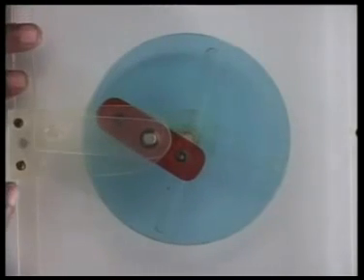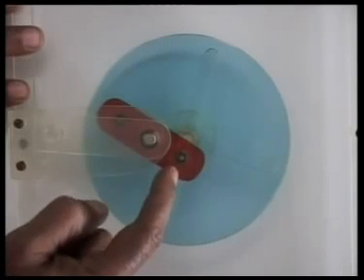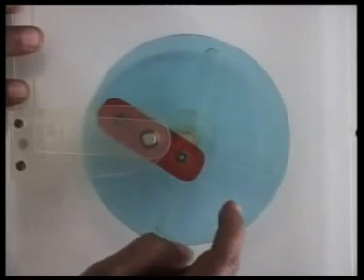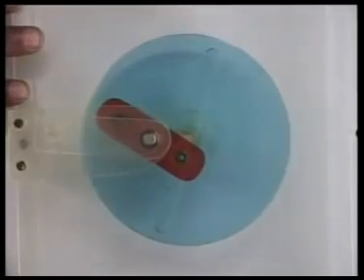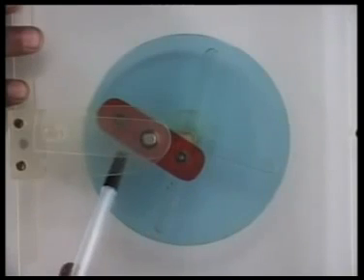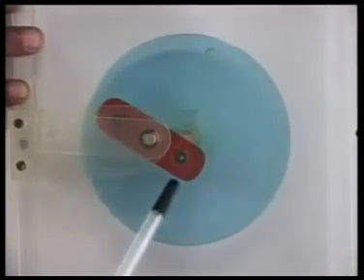Now I shall demonstrate this cross-slider trammel through a model. Let us now look at the model of this cross-slider trammel. This is link number 3, which has a revolute pair with the fixed link here. This is link number 5, which has a revolute pair with the fixed link here. And there are two sliders, 2 and 4, which are hinged to link number 3 here, and these two sliders move in these two perpendicular slots.